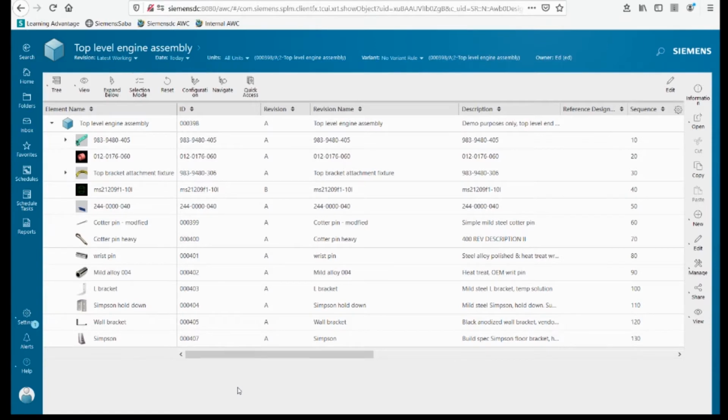And we do that by using something called occurrence effectivity, sometimes called structured effectivity. And we can specify the actual occurrences of a part in a structure that are in effect, and we can do so by specifying a date range or a unit number range. Today's example will be using a unit number range to demonstrate this capability. So we can define the units, specified by numbers, that will define a cut in and cut out range. So let me show you what that means.